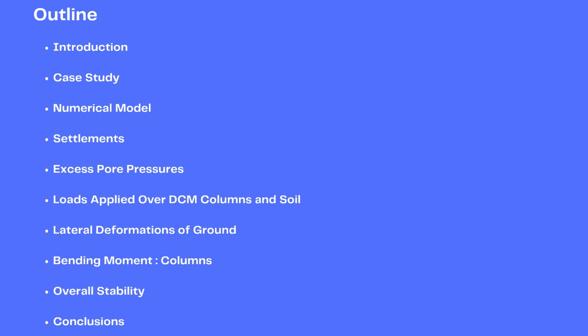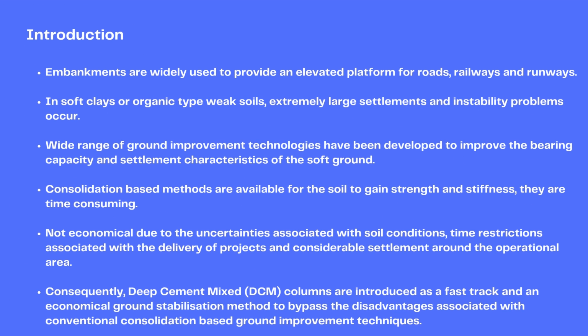Then I will compare the results obtained from the finite element model with the case study measurements from the field, such as settlements, excess water pressures, loads applied over DCM columns and soil, lateral deformations of the ground, bending moment of columns, and the overall stability. Finally, the conclusions. We all know that embankments are widely used in infrastructure projects to provide an elevated platform.